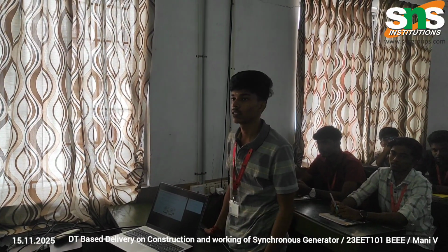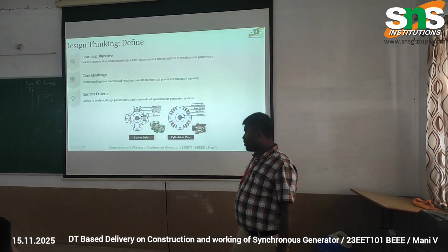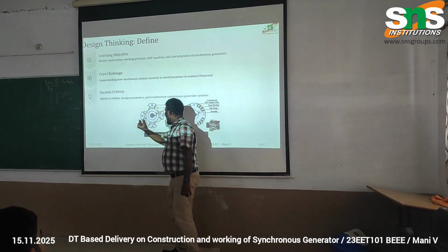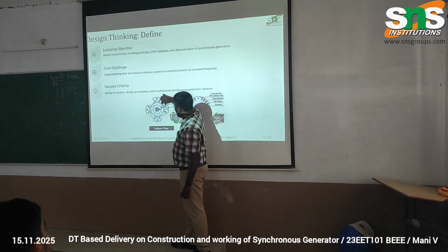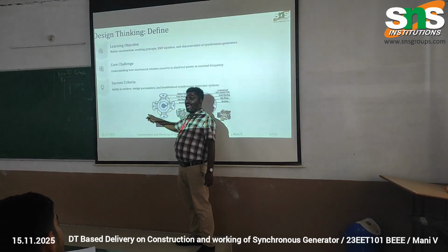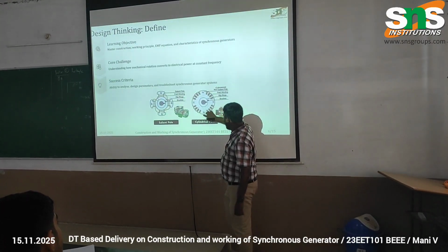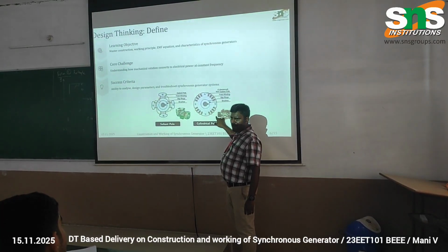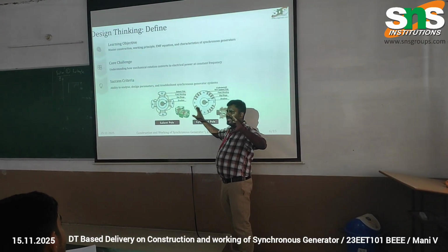Okay. So as a statement, in the salient pole machine, the air gap is not uniform because here the air gap is very minimum and here the air gap is maximum. So here minimum, here maximum, so you are getting non-uniform air gap. But if you go for the cylindrical pole, the air gap is always uniform. Now, what is the drawback of non-uniformity and uniformity?